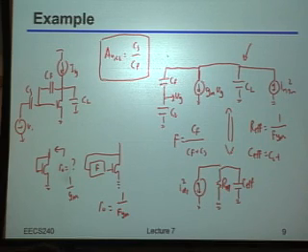And then what we have to do is put that in parallel with the series combination of those feedback caps, right? Because everything gets flipped over with caps versus resistors, that's going to be CL, and I'm going to abuse notation slightly here, but I'm basically going to say that that's CL plus CF in parallel with CS, where that just means CF times CS over CF plus CS. To abuse notation slightly less, and make the expressions a little easier, I'm going to say that that's just equal to CL plus F times CS. All I did was a little bit of arithmetic there. Does this make sense to everybody?